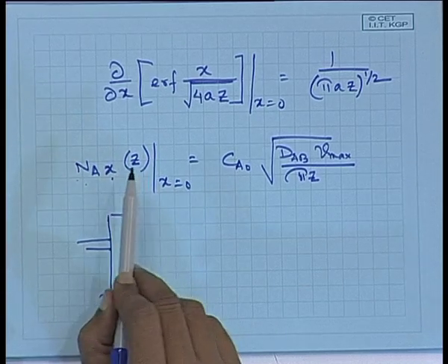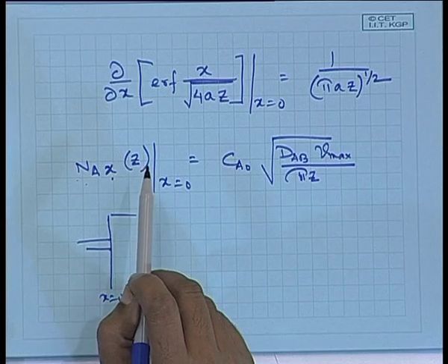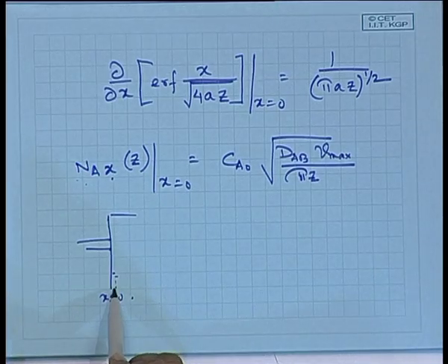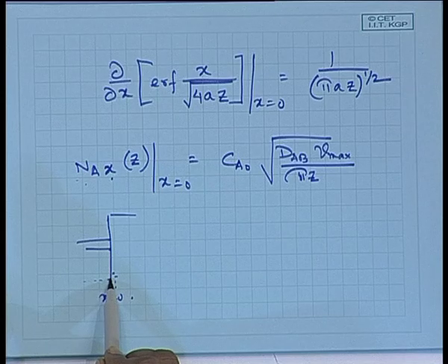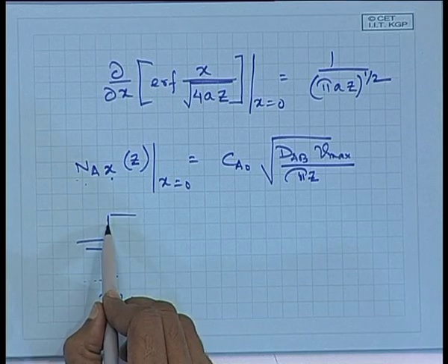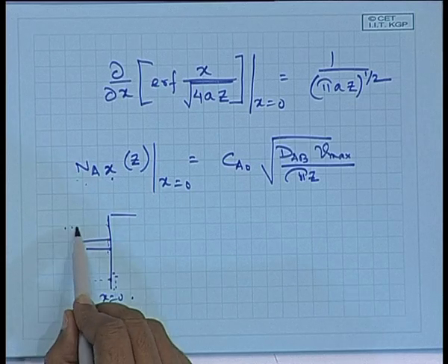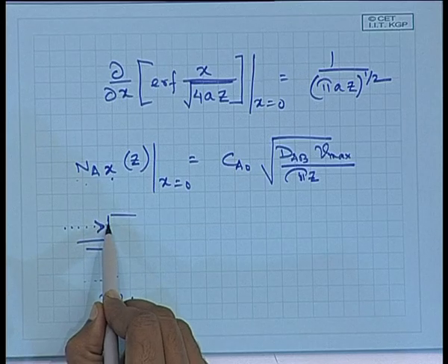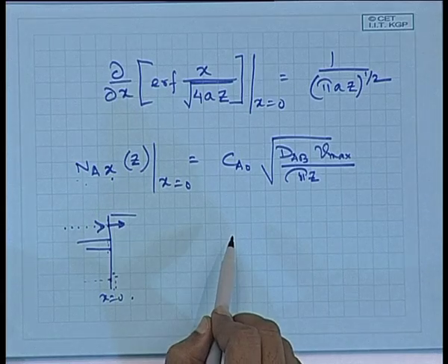Is that clear? As we have discussed, as I am going to have more and more A molecules present towards the lower portion of the film, the amount of absorption of the gas will be reduced, because I am simply making this as a control surface. Whatever motion of A molecules I have up to this point at steady state has to be diffused into the liquid film.